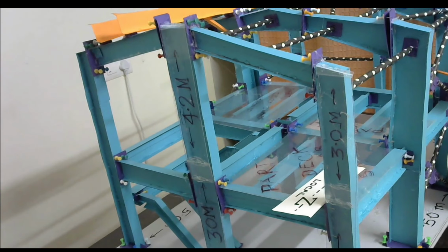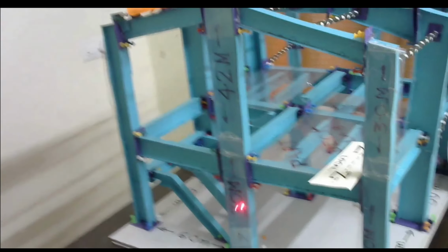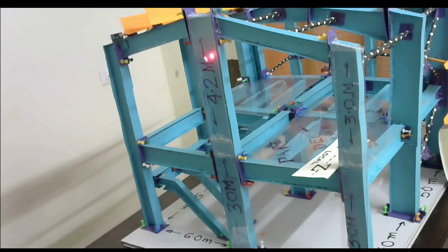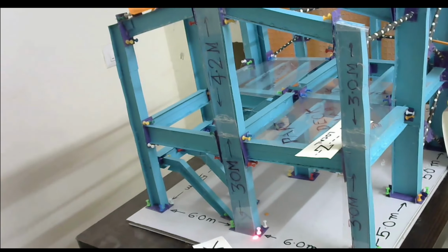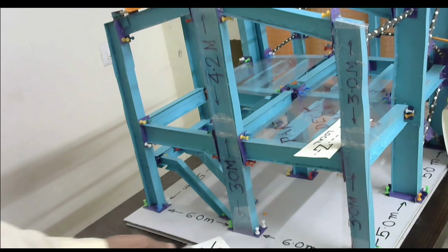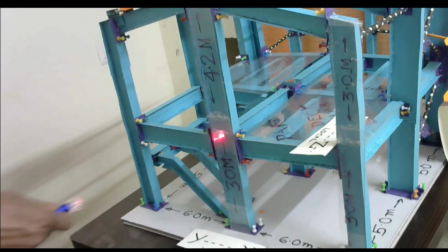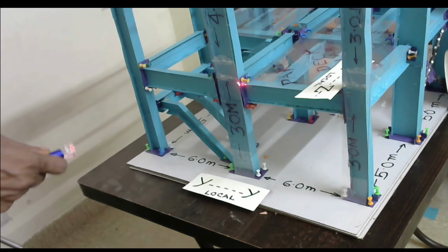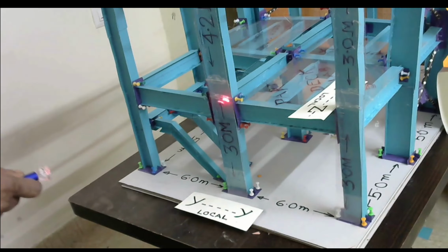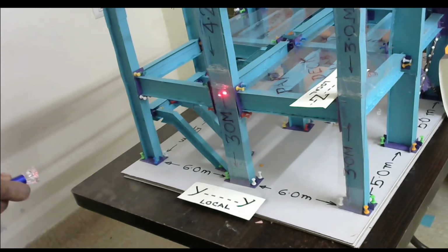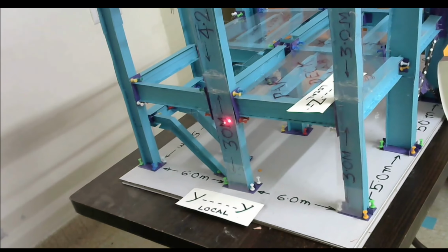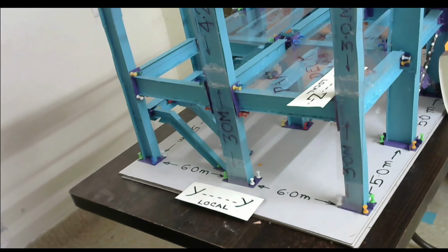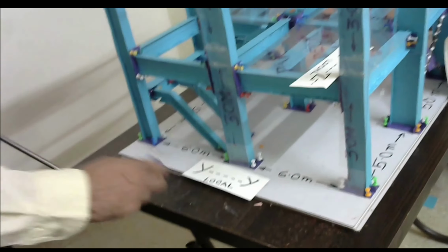Now let us come to the gable column at the middle. This is the column. LX will be 3 meter because pinned at bottom about the YY axis. The top is resisted through a moment connection, so there will be a stiffener again here, so it is resistant against twisting, so we'll take 3 meter as discussed as LX. Now when we go to the LY parameter, again bottom is pinned, top is pinned.